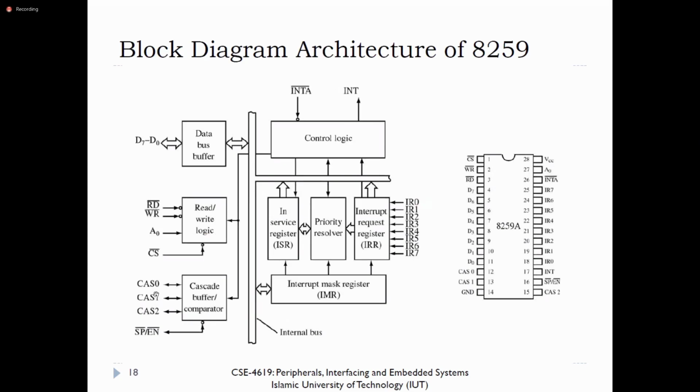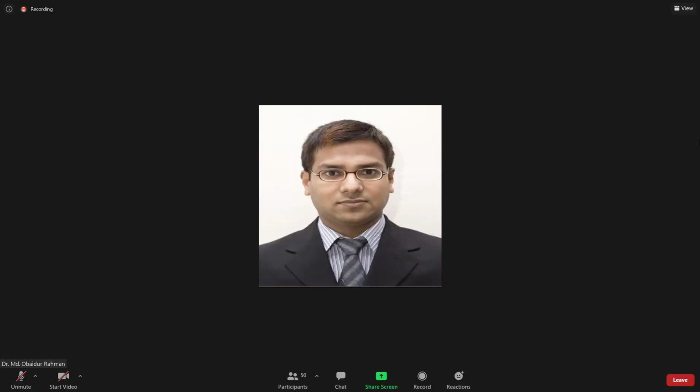And you see the cascade buffer, we have 3 cascade pins, cascade 0, 1 and 2. So with the use of these 3 pins, we may have a maximum of 8 alternatives, and through that the master considers this IC as a master node, and with that a maximum of 8 slave nodes can be selected. Now that is the thing I was showing in my figure.